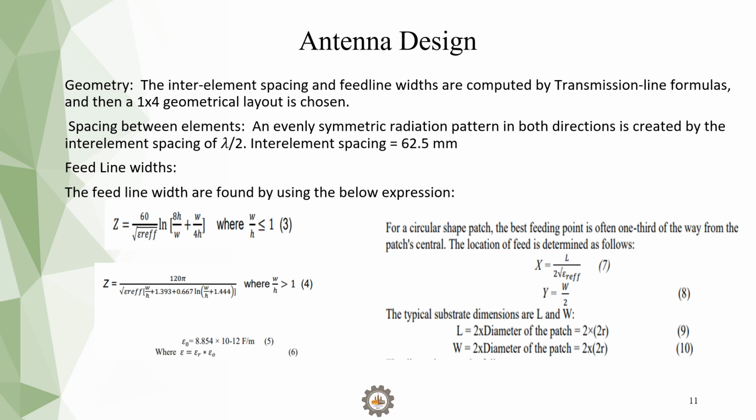After computation using equations 7 and 8, we got x equal to L by 2 under root of epsilon r reference, y equal to W by 2, where L equal to 2 times the diameter of the patch and W equal to 2 times the diameter of the patch. Here we computed the feed location for the antenna.